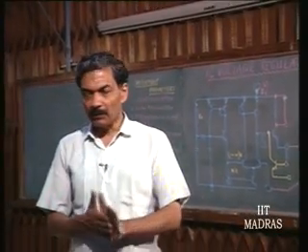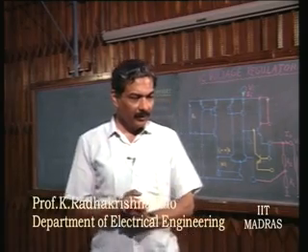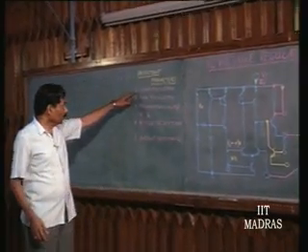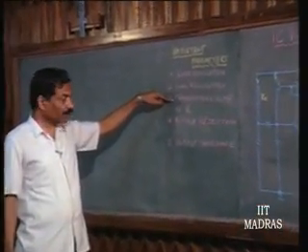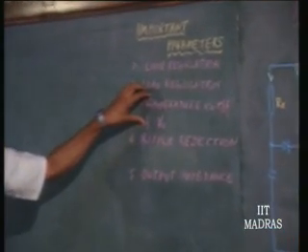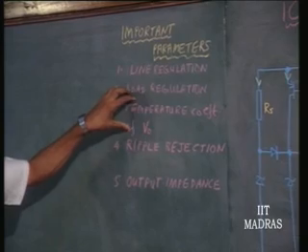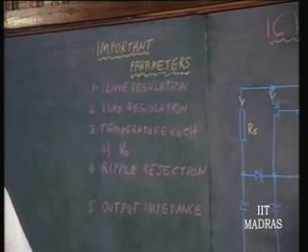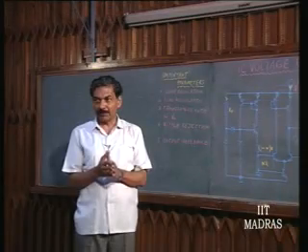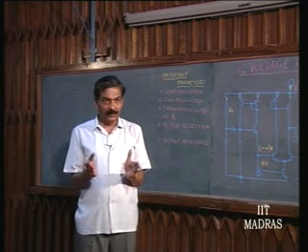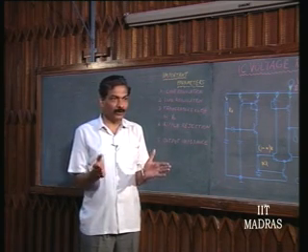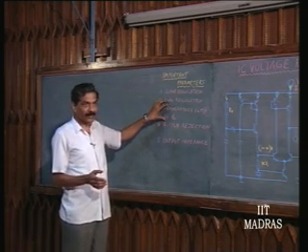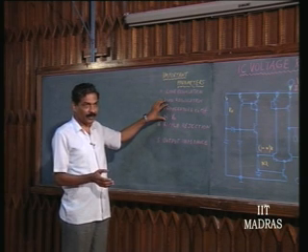Last class we saw something about voltage regulators, how important parameters like line regulation, load regulation, temperature coefficient of V naught. Now, this is something that I did not mention, but it is also equally important. Temperature coefficient of V naught is obviously dependent upon temperature coefficient of V ref, and that we have already made equal to 0. So, we are not so much bothered about that factor in the design. Already the IC designer has made it very close to 0.